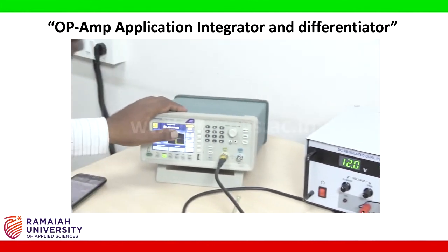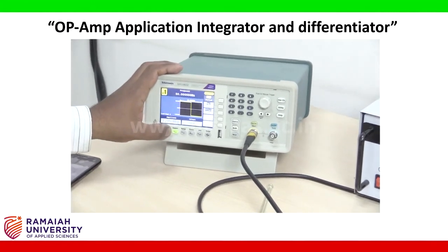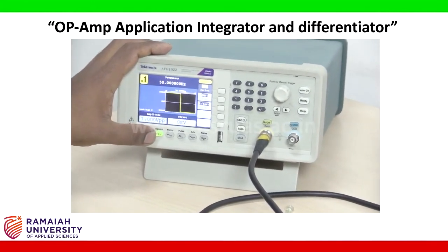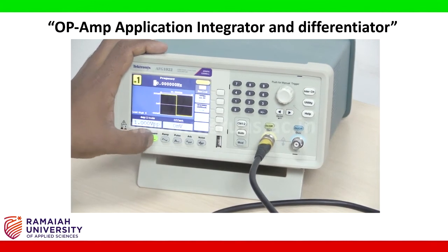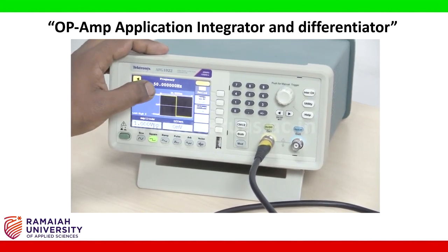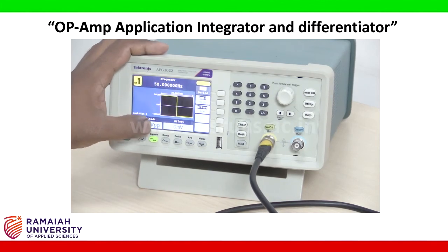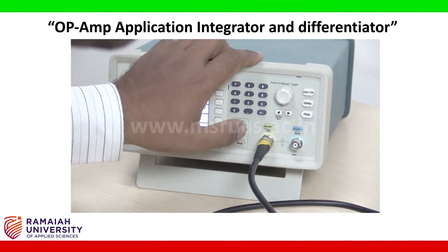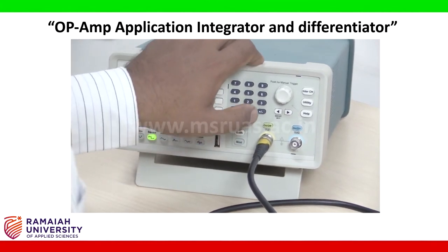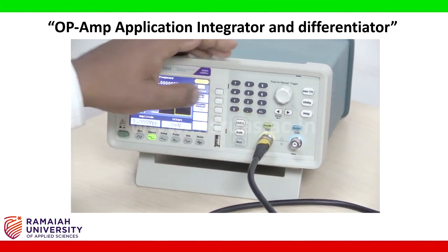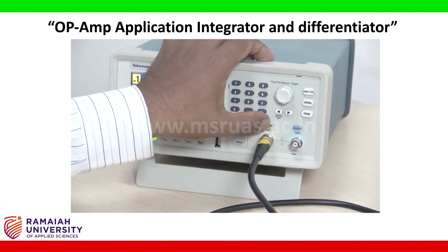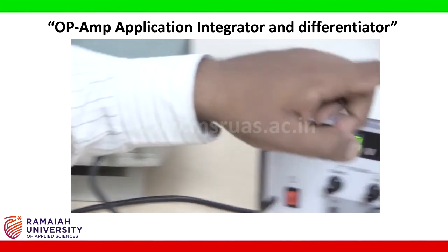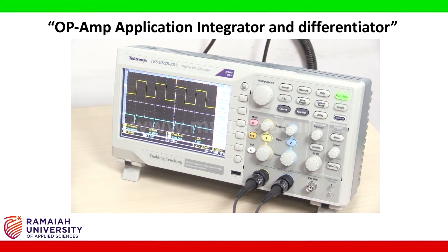Both will be set to 12 volt. Now you see here, if it is a linear waveform, you don't worry. So you put that into a square wave signal and you adjust the frequency to 50 hertz and the voltage is 1 volt peak to peak. Then you switch on the output terminal to 1. Now you see this is the output of a differentiator.